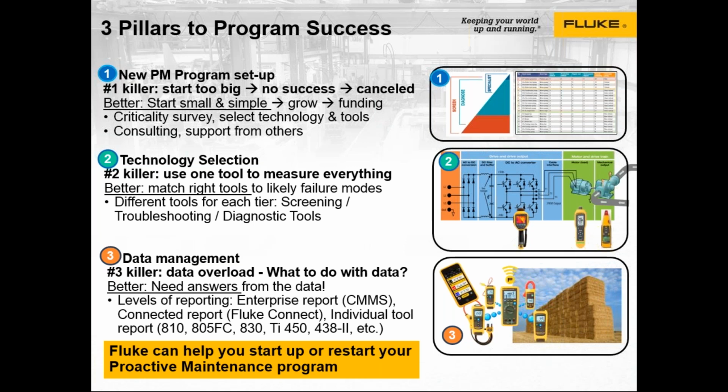Again, in an ideal world, we would get corporate buy-in from the very top, the CEO and everybody down would say, we're going to go from reactive maintenance to proactive maintenance, and we're going to use vibration, thermography and electrical testing, and we're going to start this program up. If you had something like that, it's probably going to take 2 or 3 months just to set up the program, and then it's probably going to be 6 months or longer before you start seeing some results.